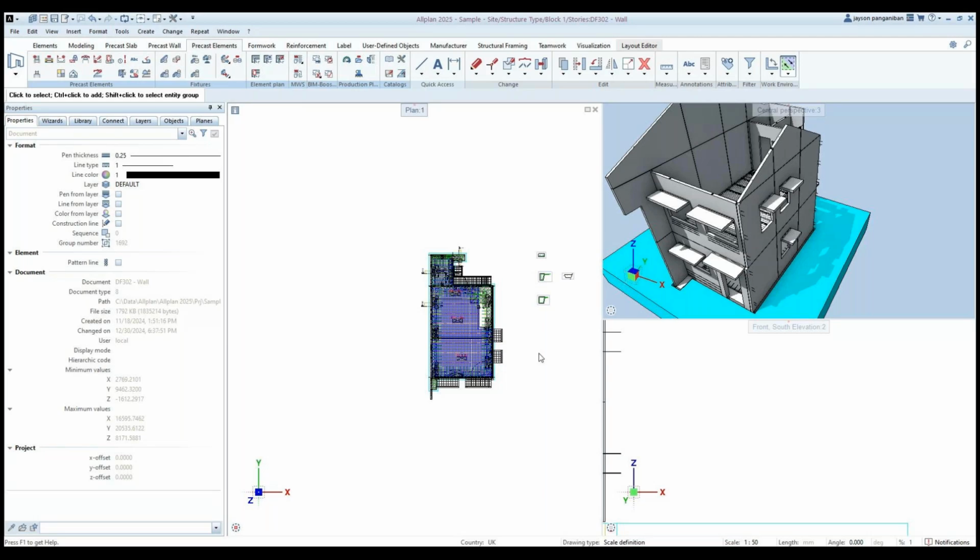So I say okay. Here you can see if I select the precast only, I have some unchecked parts here. If I say fixture and reinforcement only, all of them are still activated, but I need to see only the fixtures. So I don't want to see some slab marks, so I can remove those. Reinforcement, yes. Just to show you what you can define here. The marks, yeah, you can leave them, or just remove them. We just leave the fixtures.